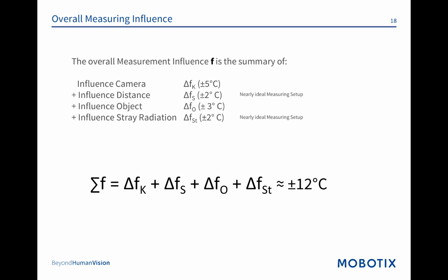So if we think about measuring temperatures with the thermal imager, this does not depend on poor quality or other things. This is just physical law. These are just limitations coming from the setup. If we make a round number, we have plus minus 10 degrees accuracy.